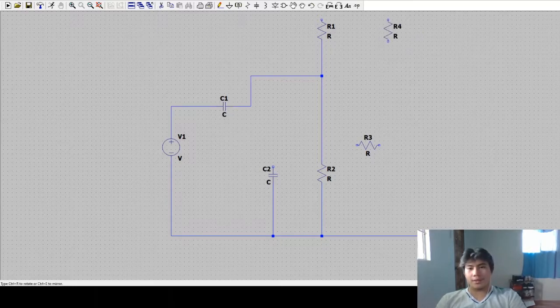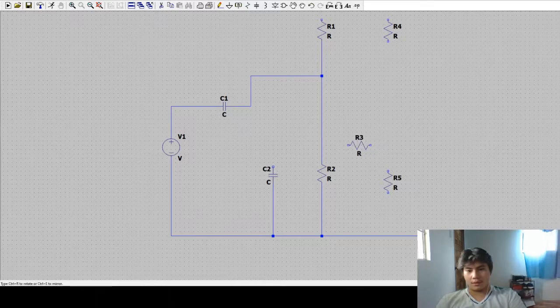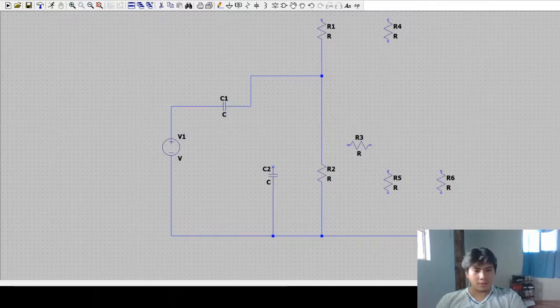A resistor here. Another resistor down here. Put that right. Need to press F7 to move. Resistor. Another resistor here. Oh, I didn't tell you, but the shortcut for the resistor is the letter R on your keyboard. So connect the wires. Oops, I need some transistor first. F2, NPN.